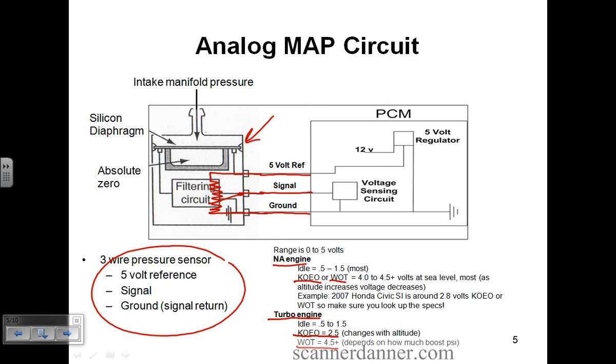Next, TPS. How did it look? Under a volt, 0.39. Did a sweep test, looked good, check mark, off the list. Next one, MAP. How's the MAP? We didn't get that far on that Honda, we didn't need to, but this is what I'm thinking about when I'm thinking about MAP sensors. Now, 0.5 to... that's really not accurate, that's what I wrote here. I'm actually thinking about 1.5 to 4.5 volts is what I typically see on a MAP. This 1.5 volt signal would be idle. And this 4.5 volt would be key on, engine off, or wide open throttle.